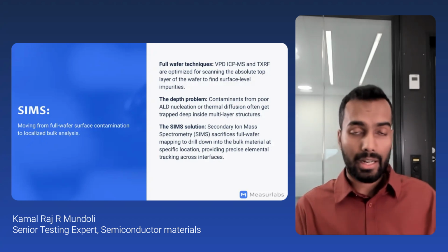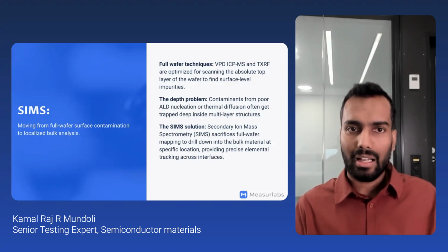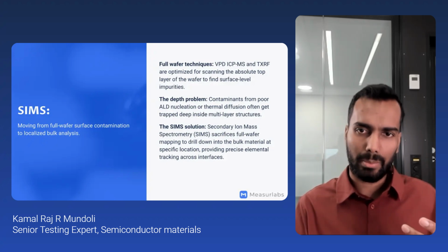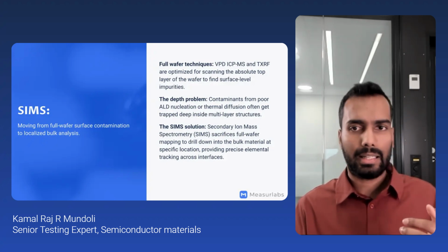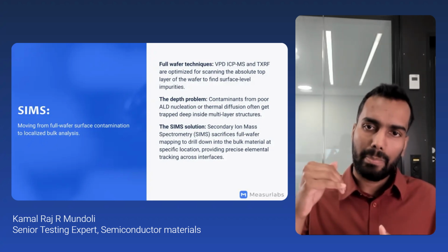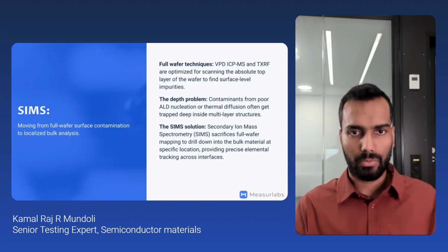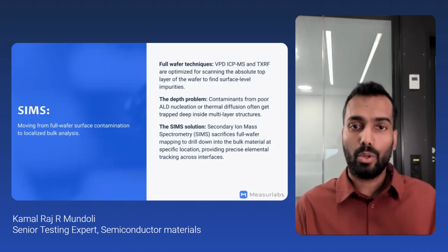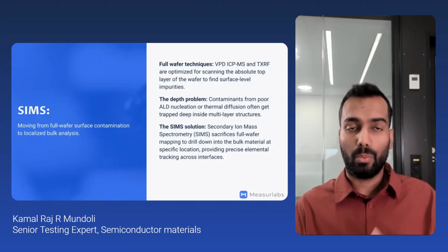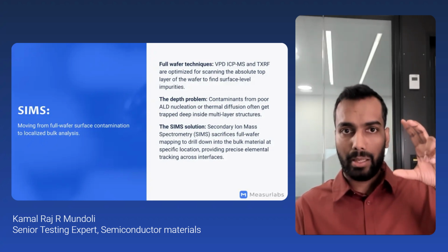But in advanced manufacturing, we encounter the depth problem. Because during complex deposition steps, contaminants from poor ALD nucleation or high temperature thermal diffusion can often get driven down and trapped deep inside multi-layer structures. So a surface scan will look perfectly clean, even though the device is failing electrically, while a VPD ICPMS taken